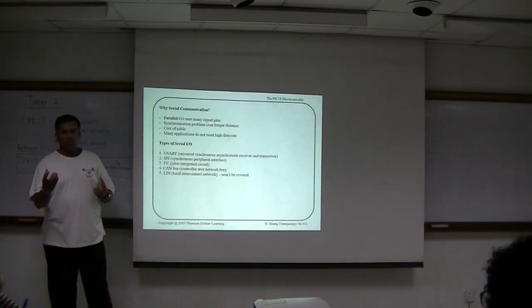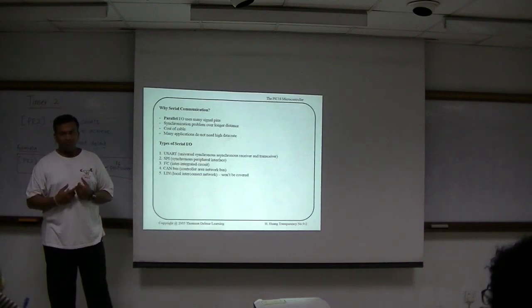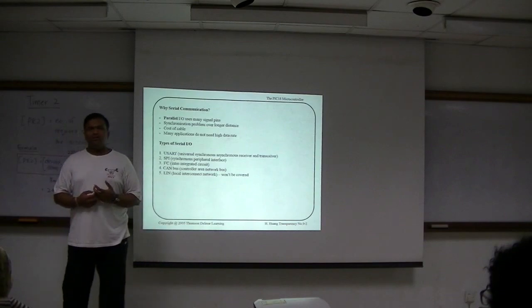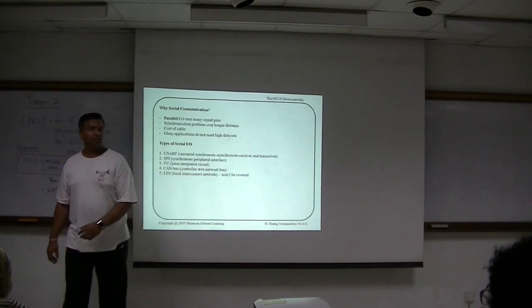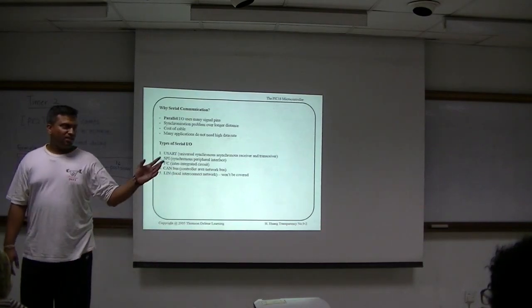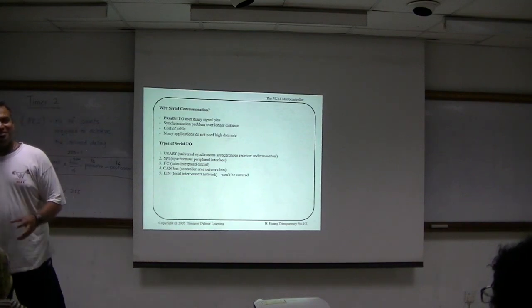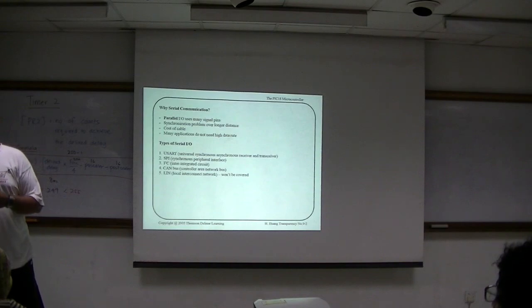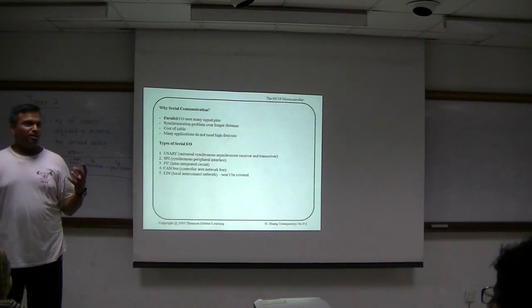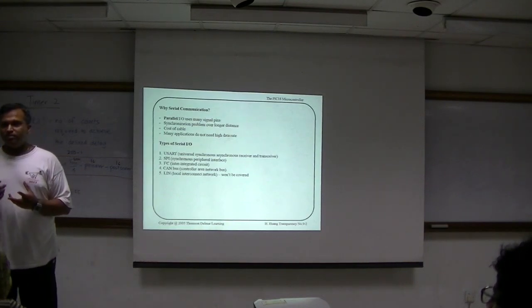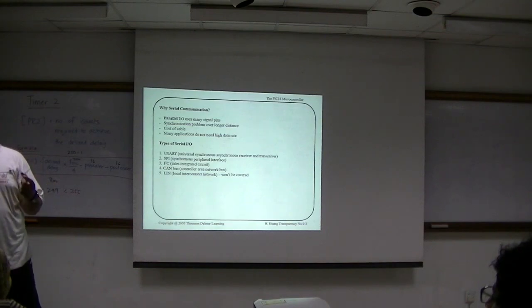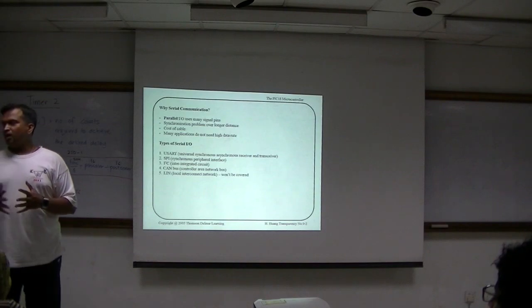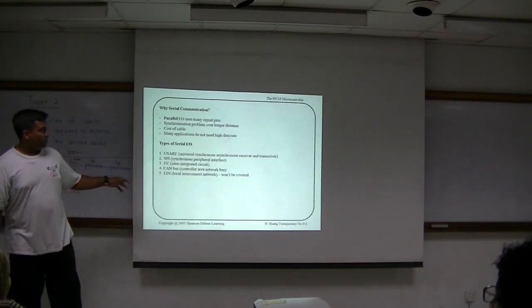This means you have a lot of controllers. All these controllers are actually connected by a network. Inside a car, you can see this CAN bus. Modern cars have one microcontroller for your fuel injection, another one for other functions, but all these microcontrollers are actually connected together. There's one ECU which controls another controller which controls all the different parts of the car. So this is very useful.